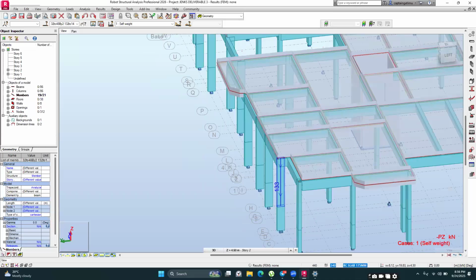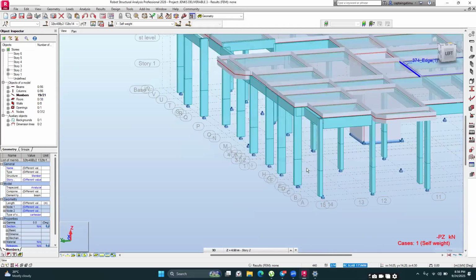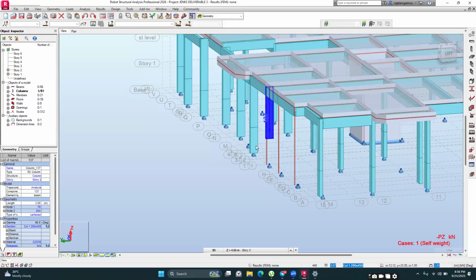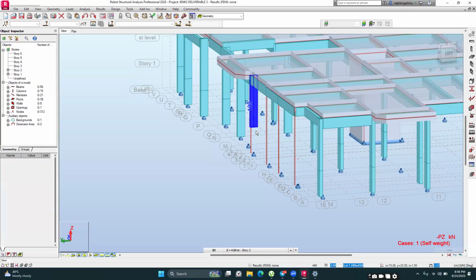With your model, what you should do is delete these columns here, so that you remain only with the sections that do not have properties. This is my assumption, because I wasn't there as you were modeling. My assumption is that you deleted a cross-section, and after you deleted it, there were remnants that remained.